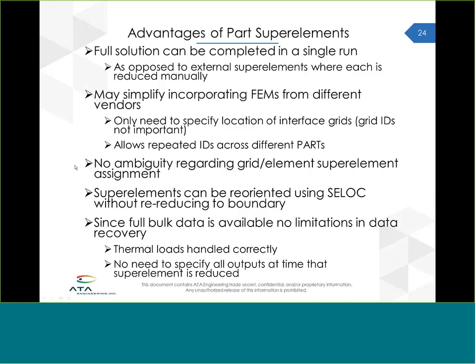It's pretty easy with part superelements to tell which portions of your model are within which superelement, because it's right there in the Nastran deck. Just look for your begin bulk statements, or sorry, begin super statements, and that defines it for you. You can instance parts of your superelement. So if you have two reflector arrays, instead of having Nastran reduce one and then reduce the other, even though they're identical, you can use that SE-loc bulk data card to say, take that reflector that you've already reduced and make another instance of it over here in this other location with being reoriented.